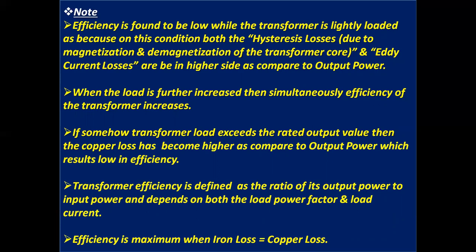Again, I repeat, efficiency is found to be low while the transformer is lightly loaded, because in this condition both losses are on the higher side as compared to output power.